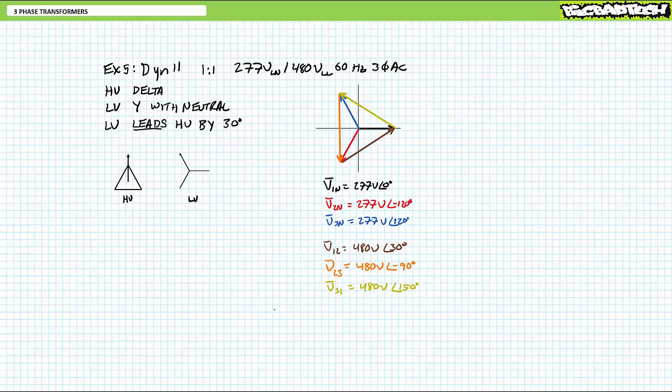The high voltage side is delta configured, so you draw it as a triangle with a reference line to the virtual neutral voltage pointing straight up. This is the reason I made the characteristic decision to employ the line to neutrals as the reference, even though we're making use of a 3-wire delta configuration.